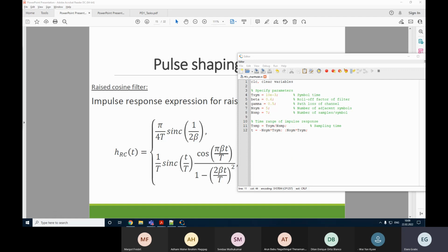So you see, for finite impulse response filters, there is a condition under which the phase frequency response is going to be a linear function. That's exactly what we want to do. The condition is very simple: the impulse response must be symmetric. If the impulse response is symmetric, then this FIR filter will always have ideally linear phase frequency response. That is quite simple to achieve. The symmetry can be positive or negative, meaning we can have either the same signs of the symbols on this side or opposite signs. This is called antisymmetry. Either a symmetric or antisymmetric impulse response will produce a strictly linear phase FIR filter.